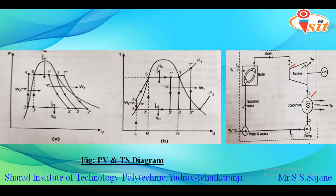During the first process, in the turbine, since there was expansion, the pressure dropped from P1 to P2. In this second process, 2 to 3, the pressure will be constant at P2, as well as the temperature T2, and the exhaust steam is condensed in the condenser, giving out the latent heat to the cooling water.